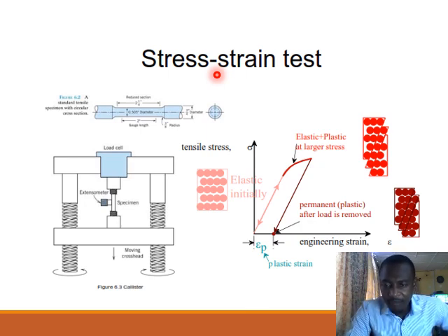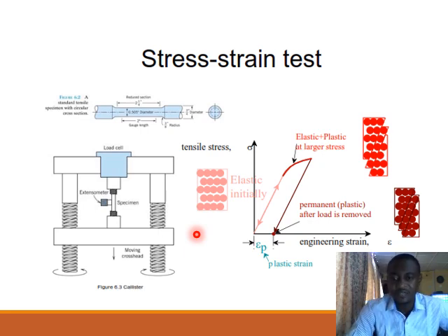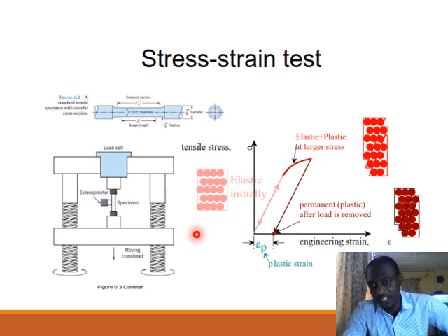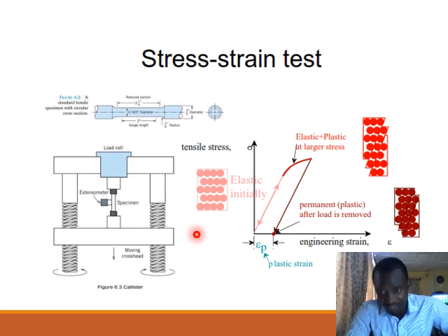Now, to measure the mechanical property, you have to subject the material to certain loading conditions that the material will be experiencing in real life during application. But basically, for the purpose of learning, we're going to look at simple loading in the form of tension and compression, and then see how that will allow you to measure the compressive stress or the tensile strength of the material.